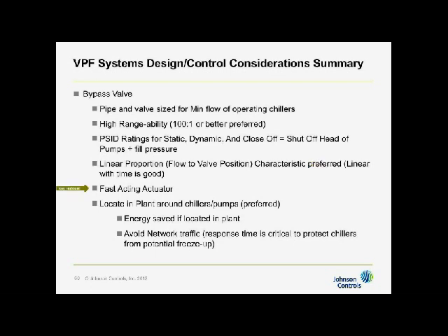It needs to be a fast-acting actuator. The fast action is needed for this to protect the chillers from freezing. Just like the control for the variable speed drives and the pumps, the control for this also needs to be fast-acting.